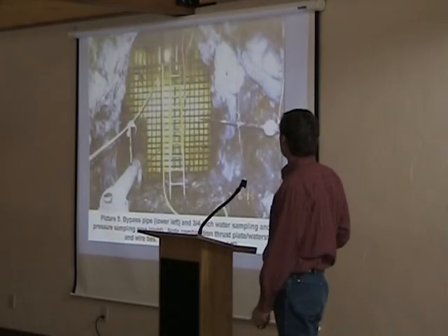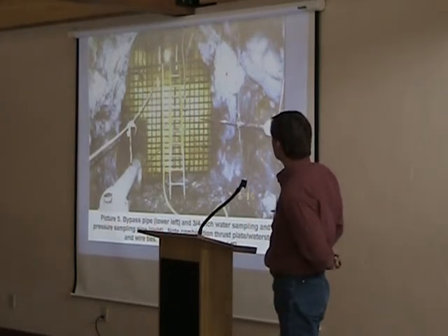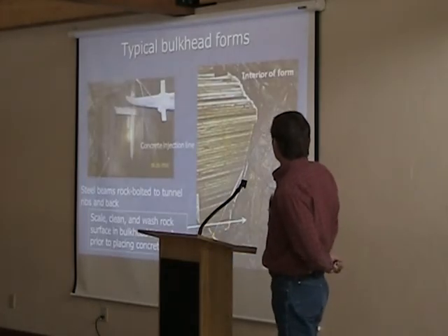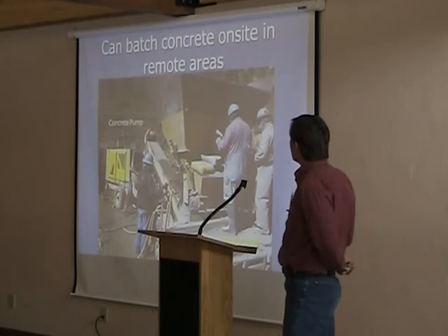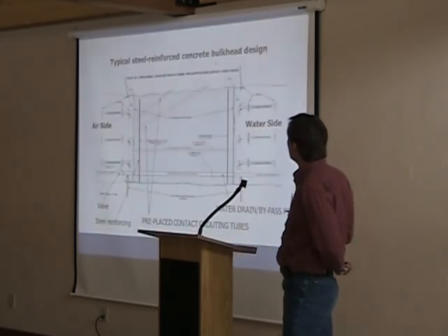So I've done my 15 minutes, and I'm just going to show a couple pictures of what these look like underground. You want to make sure you have a very clean surface. This is what it looks like behind the bulkhead before you pump the concrete. Different methods of pumping concrete. You can batch it on site, you can truck it in.